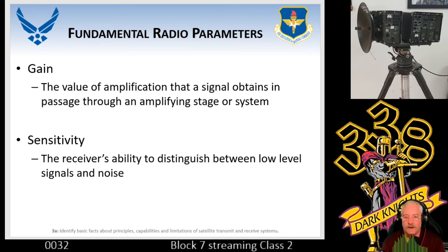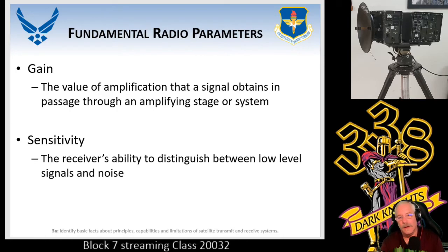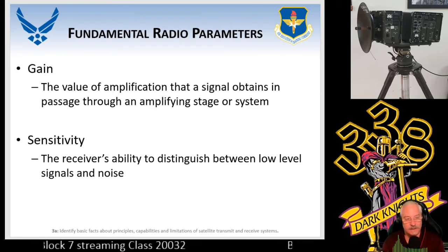Well, first of all, you got to figure out this is the threshold of what my radio is supposed to receive at. So I'm going to take that signal. I'm going to look at the signal plus the noise. Normally you're putting in a 1 kHz tone at the front end. The receiver's receiving it. You're processing it at the audio level. And the next step is to eliminate the signal. How are you going to do it?